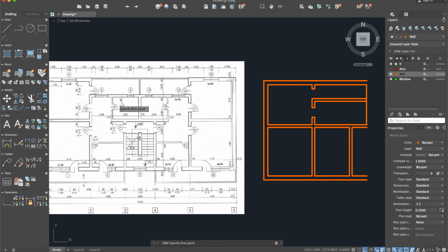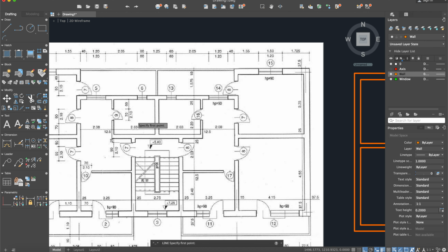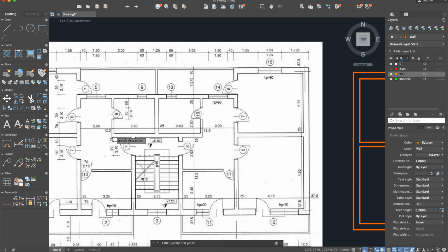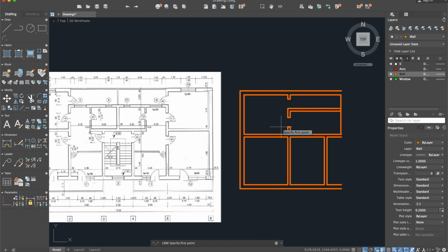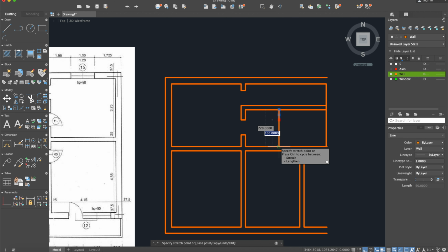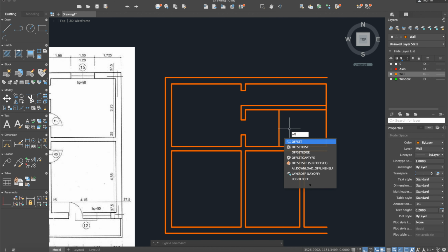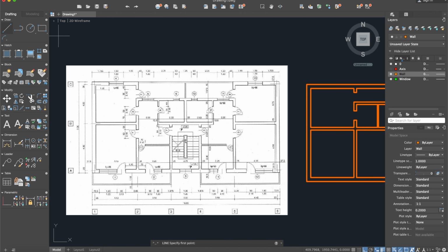Okay, here we need another door, but at the same time another wall. These two walls are not the same, so this wall is also 10. For this, I see that here there is a distance of 200, so it is exactly what I will do. I will use the offset command, 200, and I will extend this line until the surface, and offset again 10 to make our wall complete. And now this will have also a door.